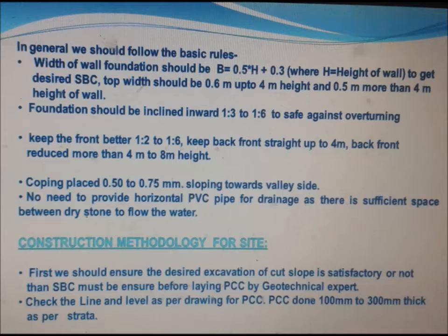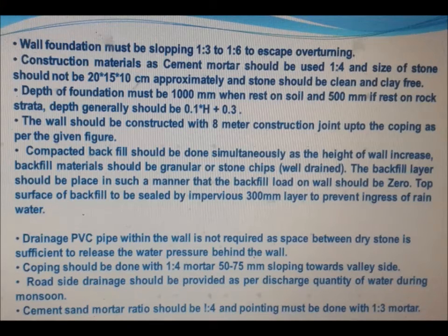Construction methodology for site. First, we should ensure the desired excavation of the cut slope is satisfactory or not. Then SBC must be ensured before laying PCC by a geotechnical expert. Check the line and level as per drawing for PCC. PCC is done 100 mm to 300 mm thick. As per the requirement of strata, the wall foundation must be sloping 1 to 3 to 1 to 6 to escape overturning.